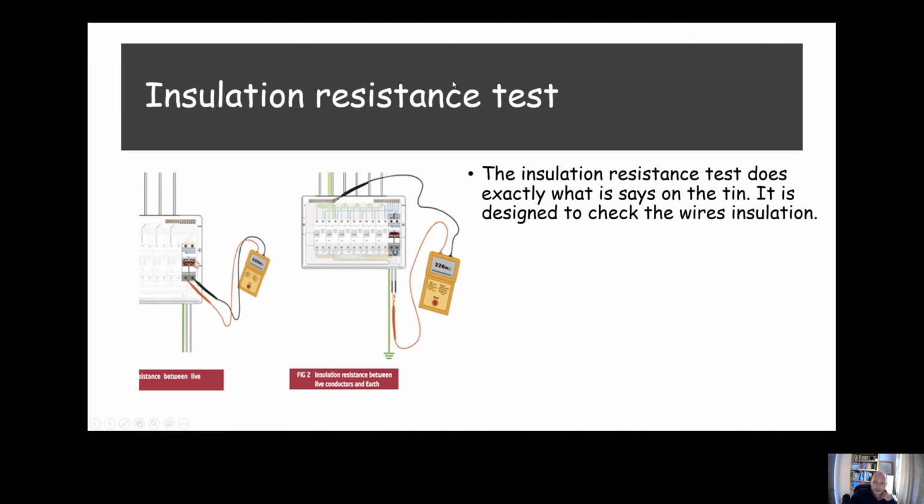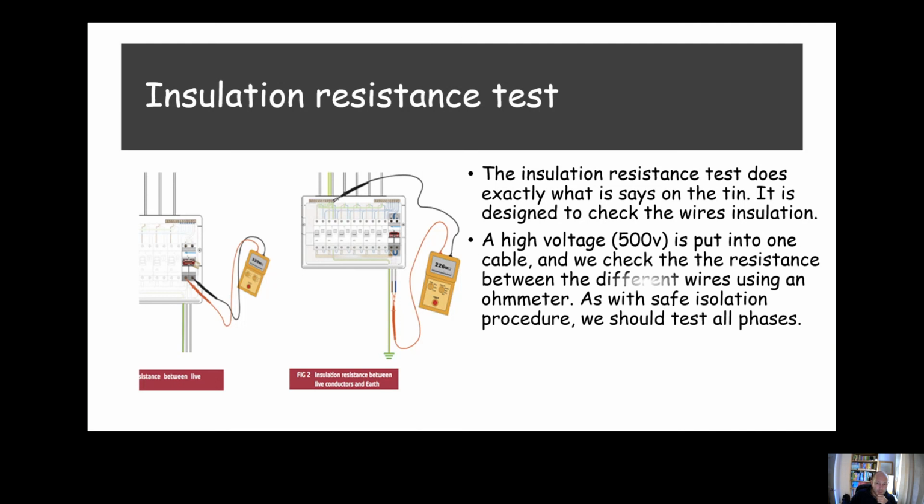Insulation resistance test. Okay, insulation resistance test, it does exactly what it describes. Its purpose is to check that the insulation between the wires is working as it should do. You put a big voltage in, you put a voltage of 500 volts, worth remembering, okay, into the circuit, and then you check the